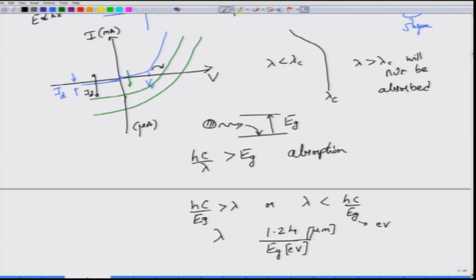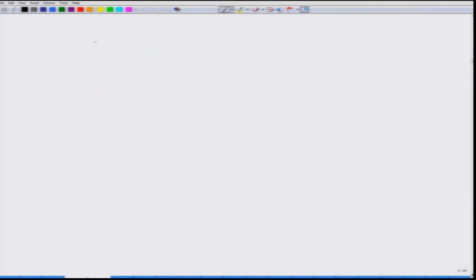A small change in the PIN will give you the APD diode. Okay. APD structure, let me first draw this, I will not draw the structure as such, I will simply indicate the layers over here. So it starts off by having a thin P plus region, a large pi region, this is the intrinsic region, but this is mostly doped with a very small amount of P material. So this pi layer is mostly a small amount of P doping. There would be one more P region, and this is important, there is an N plus region. N plus is heavily doped with donors which give you electrons.